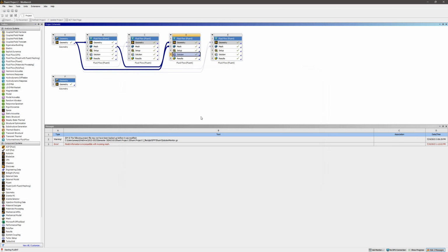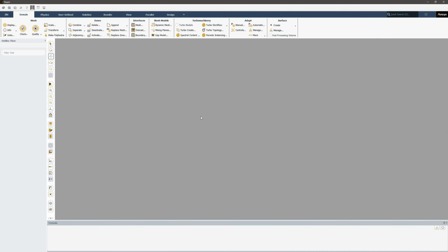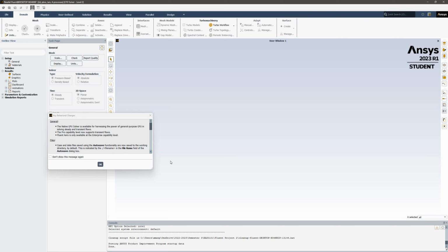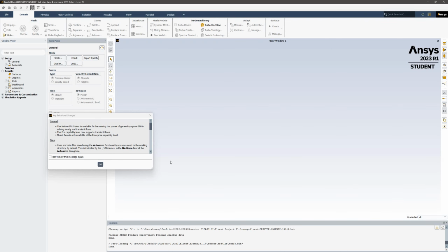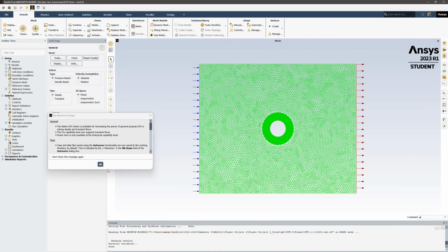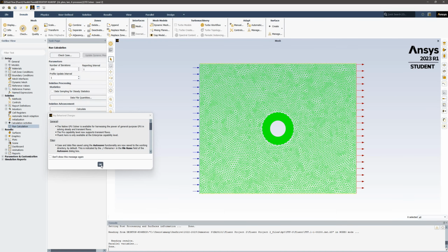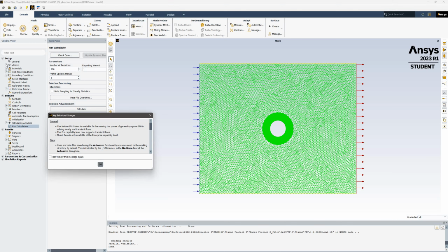So again, I'll come to solution first just so we can see the plots and the lift and drag coefficients. So normally for potential flow, you're supposed to do this inviscid, but Fluent doesn't give the option to rotate the cylinder with an inviscid model.